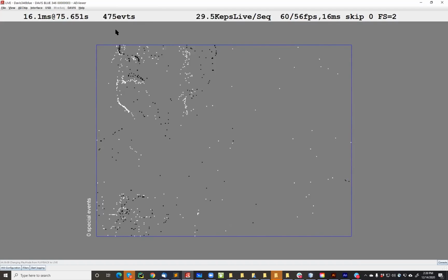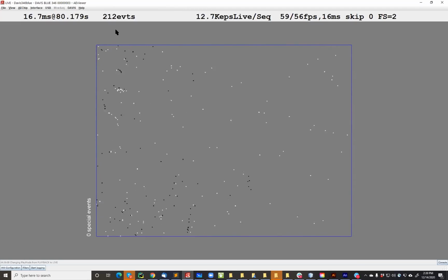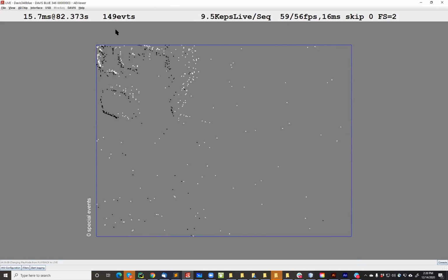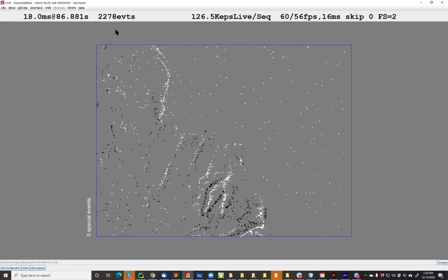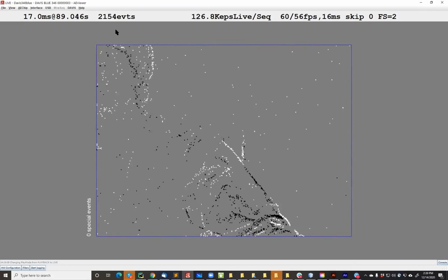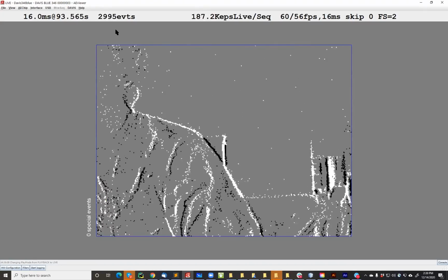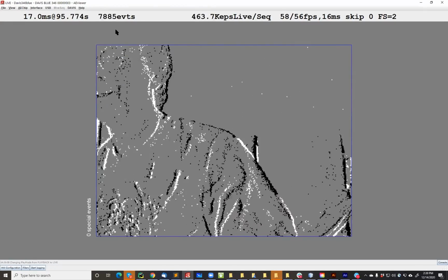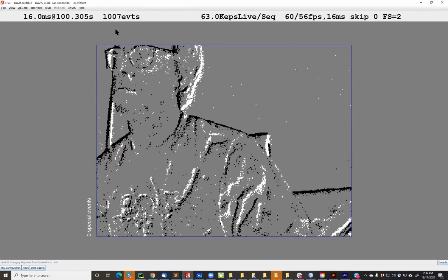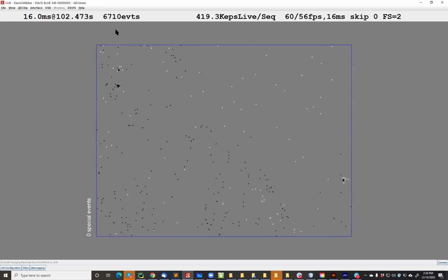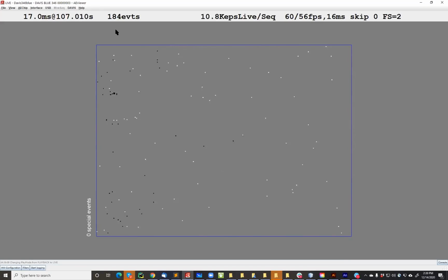So the minimum reaction time with a high-speed USB interface is about 1/8 of a millisecond, 125 microseconds. That's a pretty high-speed camera. Not super high speed, right? People are now building cameras with a frame rate of 1 billion frames per second, or even several billion frames per second. I can tell you about that some other time. But anyway, this lets you do a lot of high-speed robotics quite cheap, because the list of spike events is much sparser than the list of pixels you have in a regular camera.